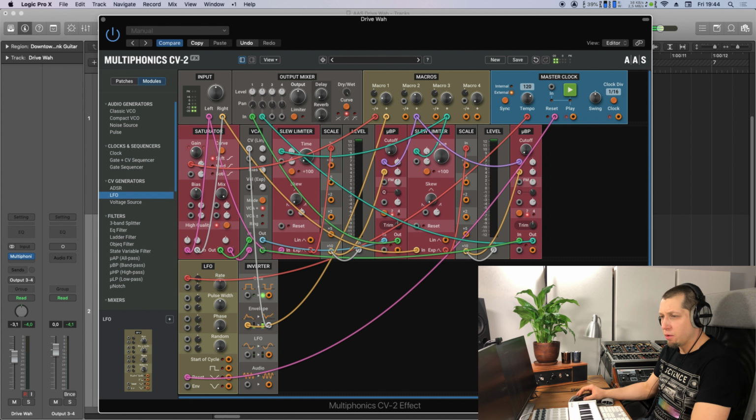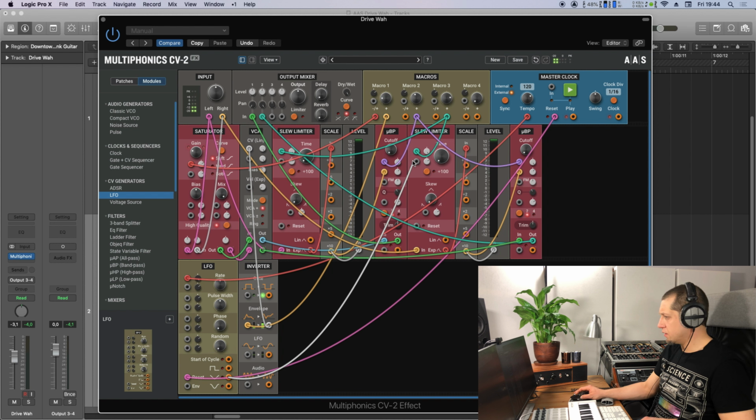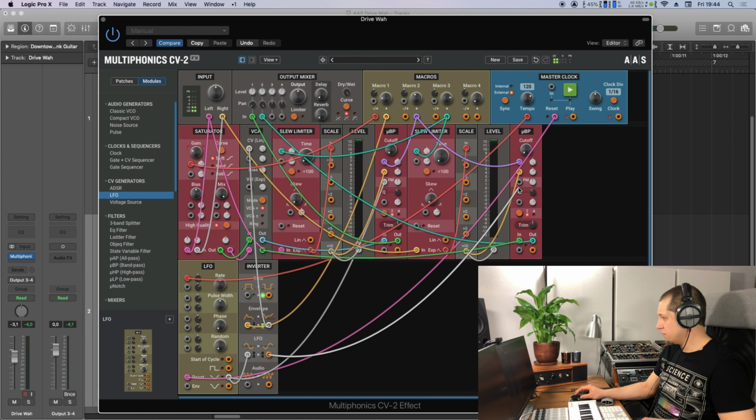So how do we do it? We can use the FM input, frequency modulation. So this basically changes the frequency of the cutoff knob also. We'll change the left cutoff in one way, and then we'll invert this LFO in the inverter we already have here, and change the second one in an opposite way.